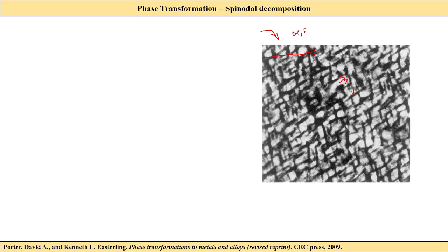Now, if the double derivative of the free energy with respect to composition is negative, the free energy change with respect to x becomes so large and negative that the final free energy becomes so negative that we can directly shun the nucleation part.